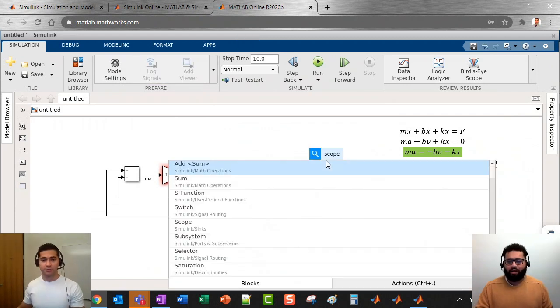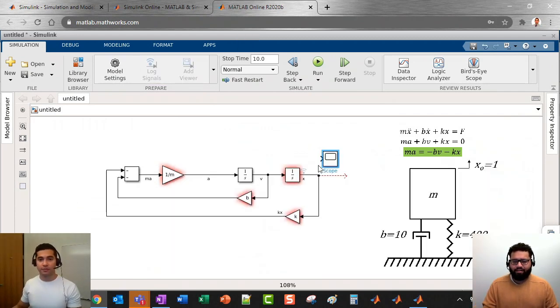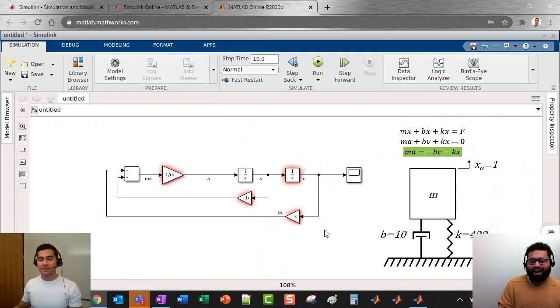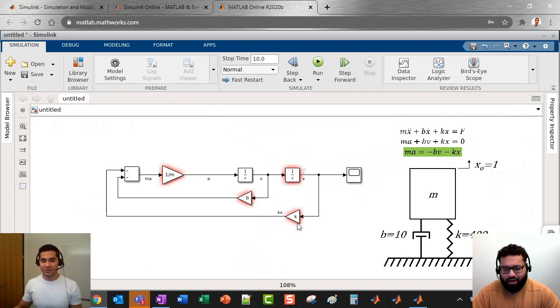Logging it means that it's going to open up in the Simulink Data Inspector view, which we can show to you in a little bit. But Ed's essentially added a quick little scope in there, which we can use to visualize our position, or our x term, over time. Exactly. We did both: we're logging it and we're going to visualize it with a scope.